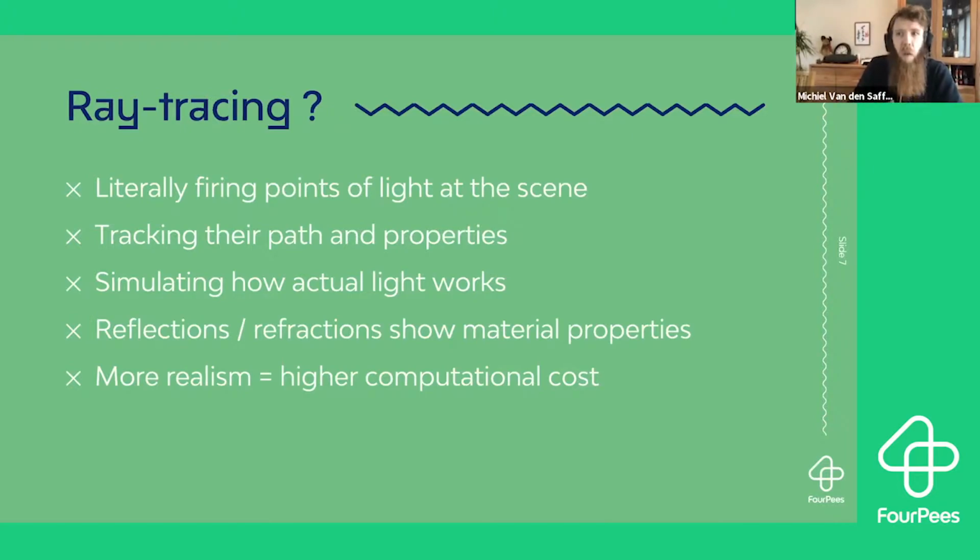So usually when you are using these exports, you are doing the exports on a separate system than the one you're working on. Usually a system that is a little bit stronger in GPU capacity than the one you're working on. That way you can do the renders somewhere else and keep working normally on your own workstation. That's why there's a separate application with iC3D called Render Manager that you can run on a separate system.